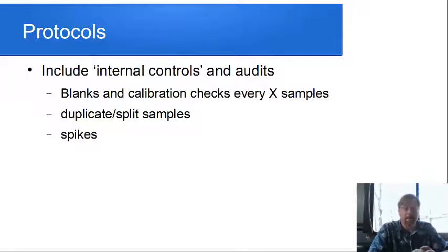This is the one that I realized just this morning that I had not understood completely. There are apparently two types of spikes. One is what you use when you are not expecting to see anything in your testing. So for nitrate and nitrite testing in drinking water, there should be no nitrates and nitrites in the water. You're not expecting to see anything. So every so often you have a sample where it includes a spike of nitrate or nitrite that should hit roughly halfway through the range.